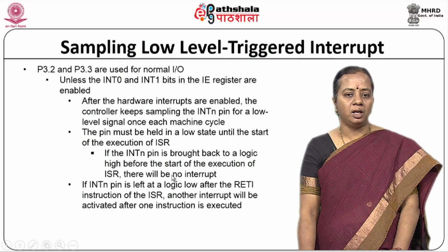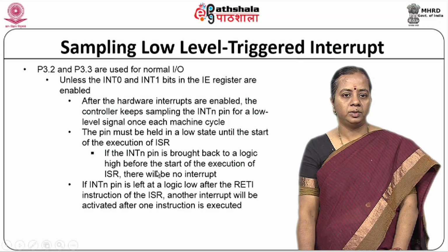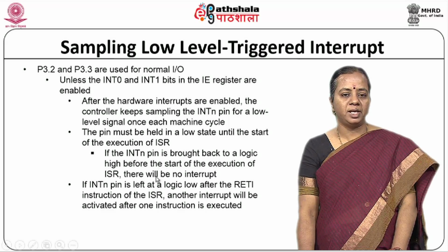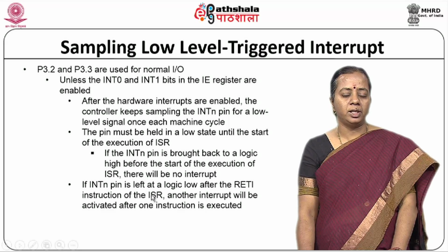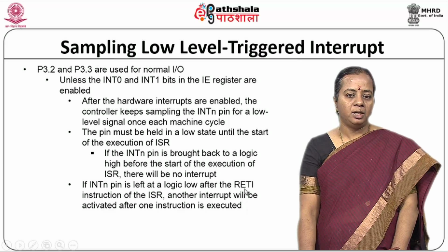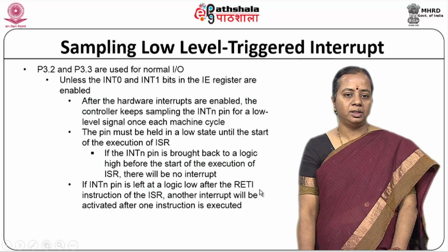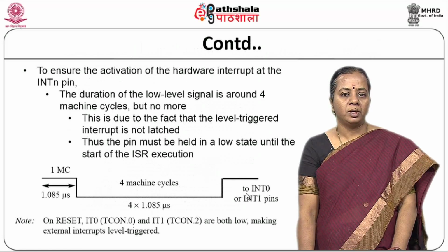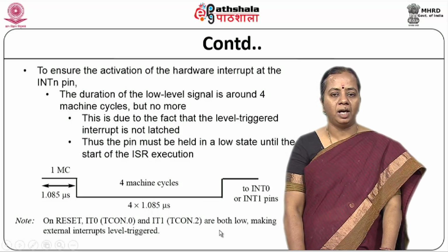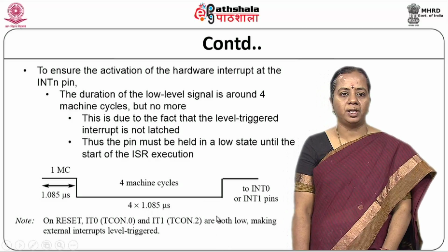So, when the IE register enables the external interrupts, then if I press it, it in turn invokes the ISR routines, and in the ISR routines we can write any of the applications. At the end we have to put RETI, which re-enables the hardware pins and in turn helps us restore many things of the main application. So, when you look at hardware interrupts, certain things have to be considered also.